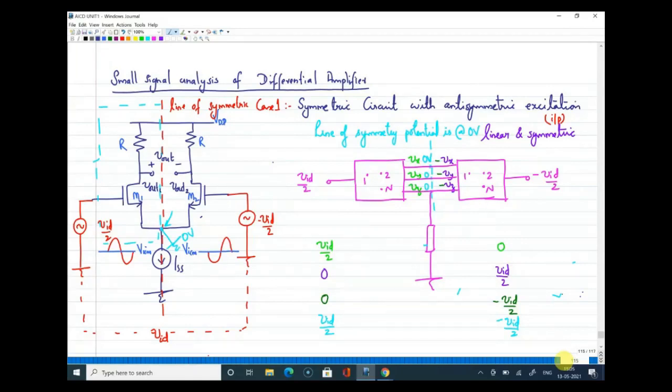A transistor is off or on depending on the DC voltage which you apply to it. So DC voltages will always be there, and that will keep the devices in saturation. Now, for small signal analysis, since there are no changes in the DC, we assume that those are zero. The meaning is that the change is zero.